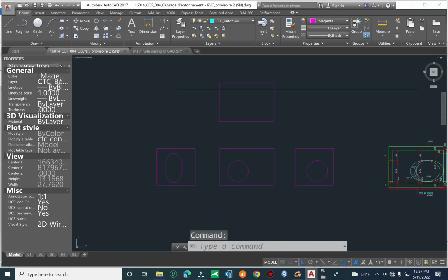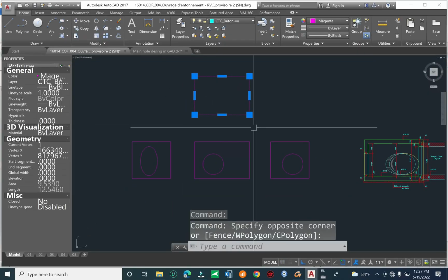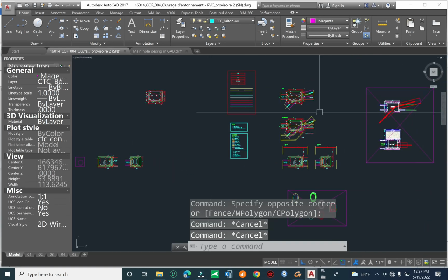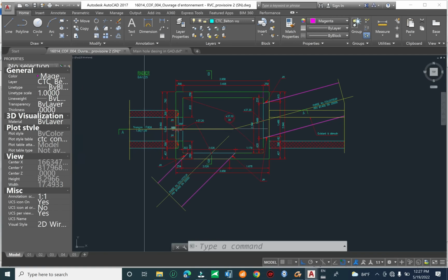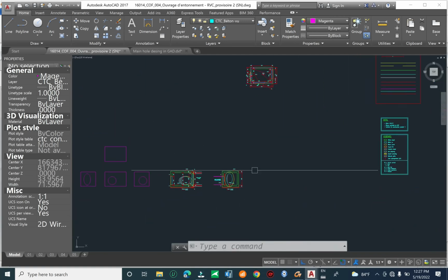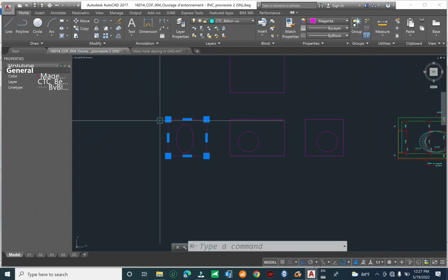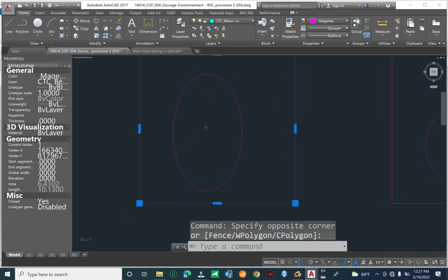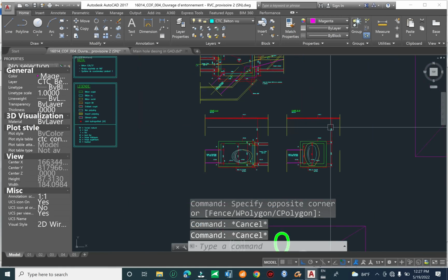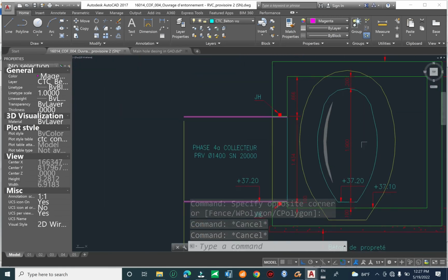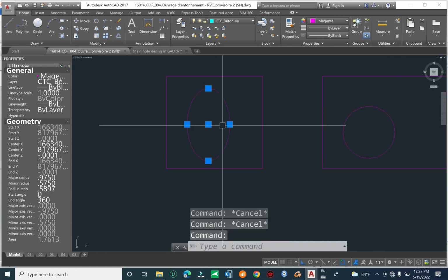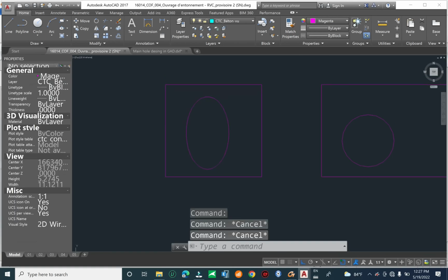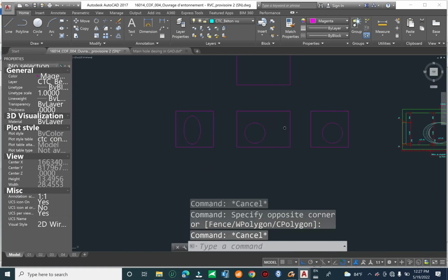When you complete modeling for the bottom and the top slab, for the front wall we call it front wall, and this is the left wall, and this is the right wall. In the left wall we have an oval shape. Actually this shape is like this one, but we can use an ellipse. You can check the property here, ellipse. So you can model it as an ellipse in this model.